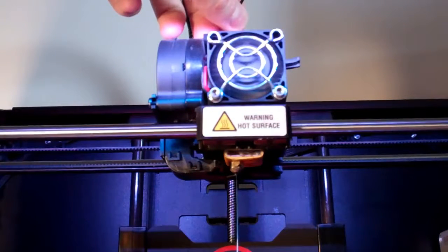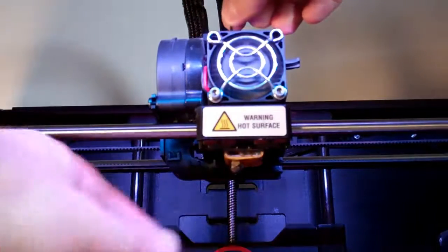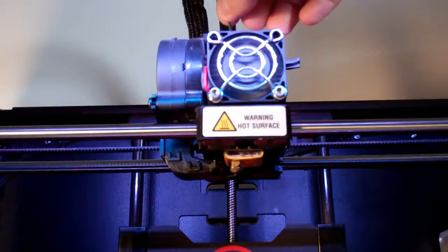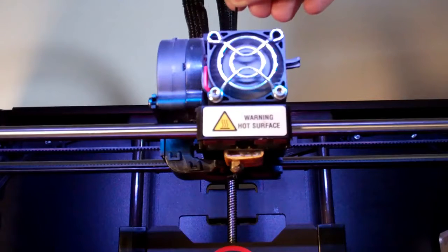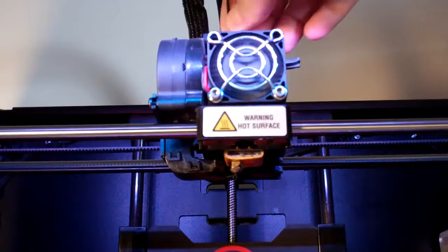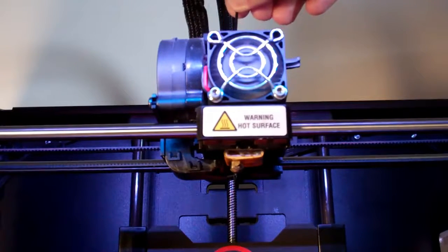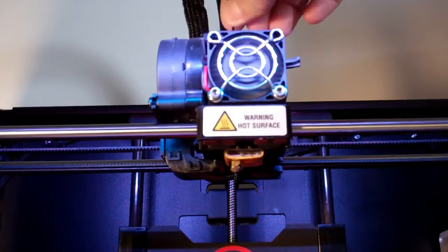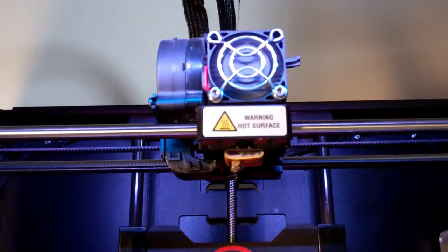There you go, you can see the red there, the heaters are coming back on. So what we do, we pull out the blue plastic from the nozzle and we pull out the ninjaflex, and then we'll reload it and do the same again. And by doing this, we're clearing out all of the PLA plastic filament that's already in the nozzle. Otherwise it will clog the nozzle if that's combined with the ninjaflex.